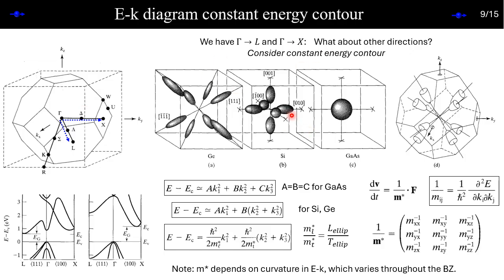Now when we are defining this constant energy contour, again we need 3 axes. We can take this kx, ky, kz. That's fine. That is working well for silicon. Because along this direction, say kx is k1, and then perpendicular to these are ky and kz, which we call k2 and k3, which are perpendicular.